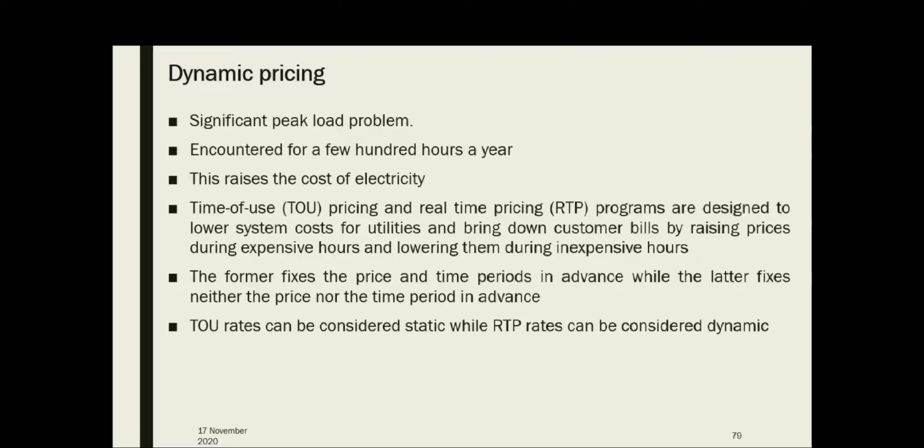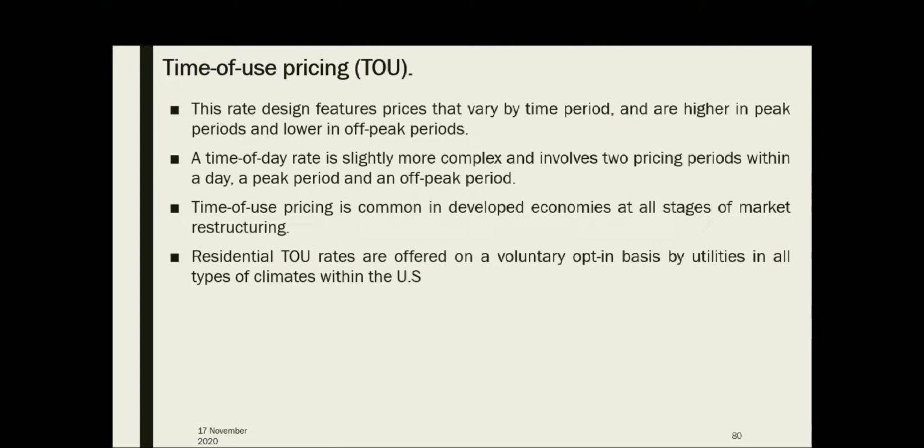A time of use rate can be considered static, while an RTP, real time price rate, can be considered dynamic. So there are various kinds of tariffs available. As you all know, in case of a flat tariff, the price remains static even though the power demand changes. So customers under such a scheme do not face the changing cost of power supply with a change in the aggregate demand, so the consumers have no financial incentives or benefit in case of a flat type tariff.